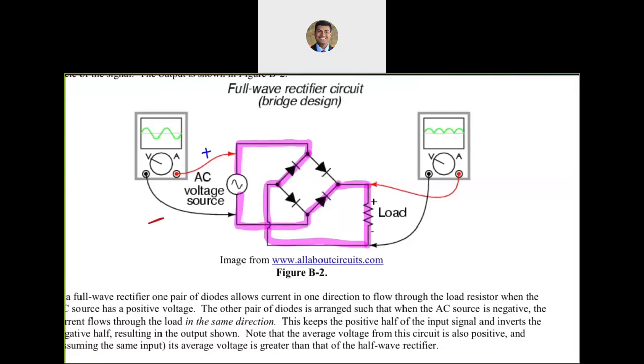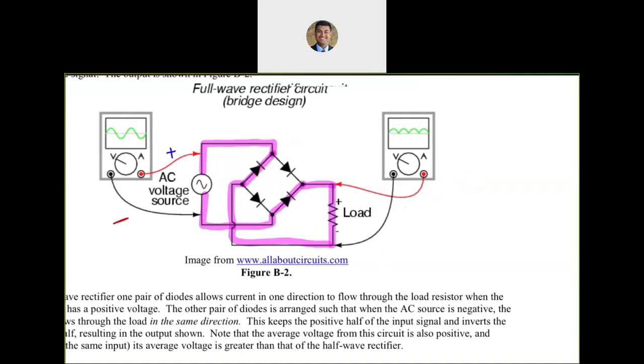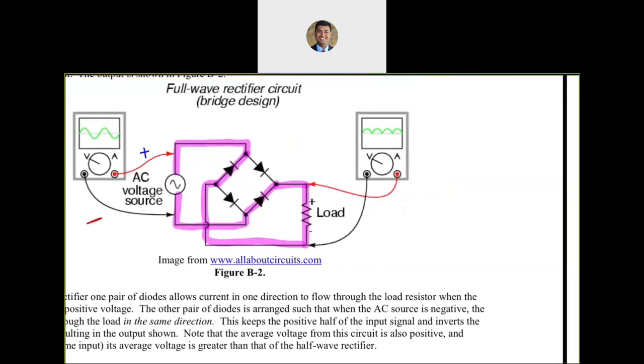And as you can see here, it is using the remaining two diodes. Again, the same deal: negative voltages minus 1.4 for the two diodes to turn on. Whatever remains goes across the load resistor there. So in other words, I will be able to see the positive voltages, and I will also be able to see the negative voltages on the diode.